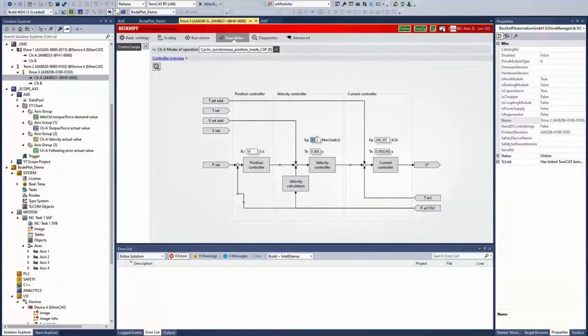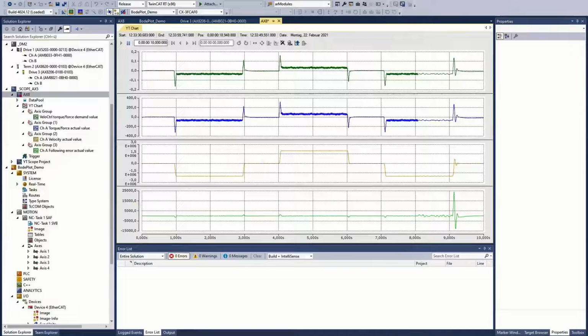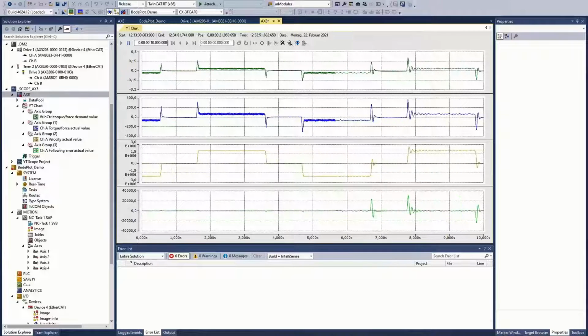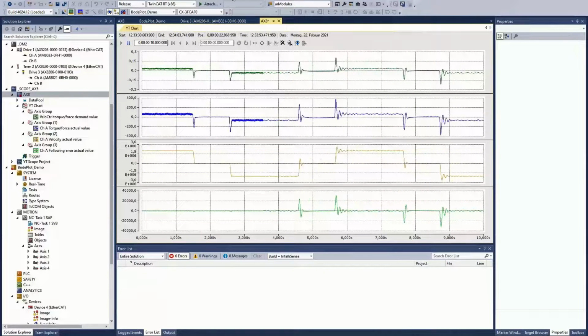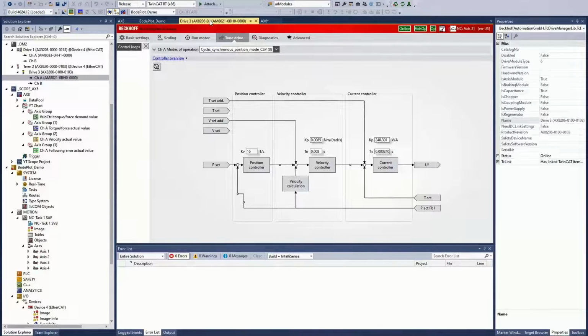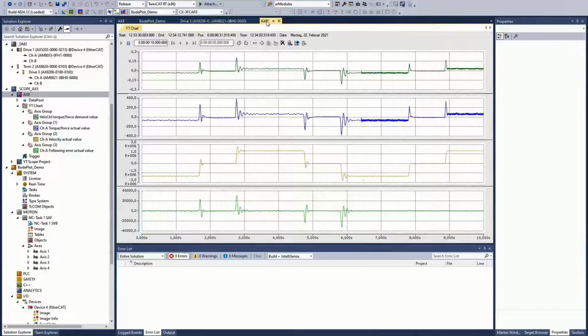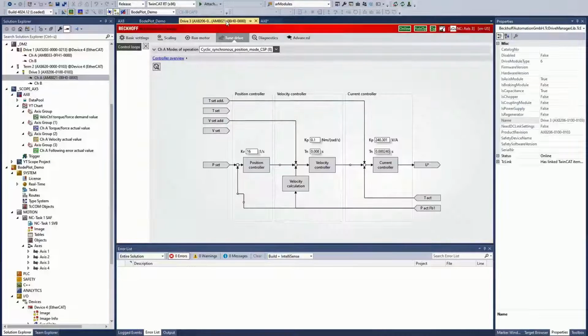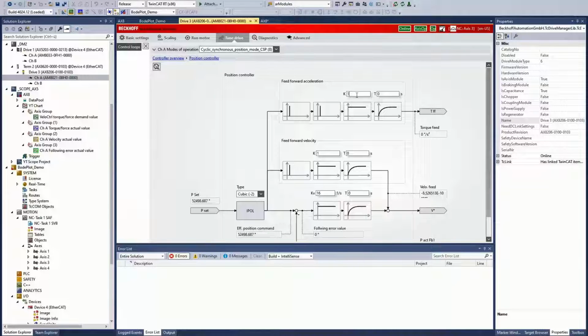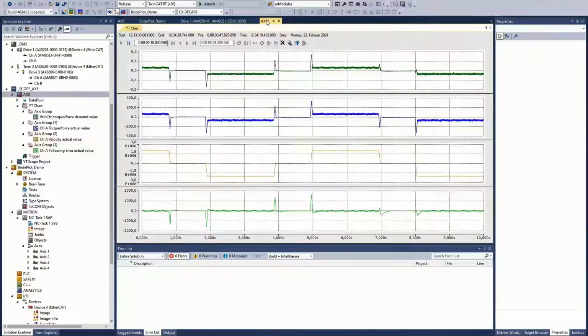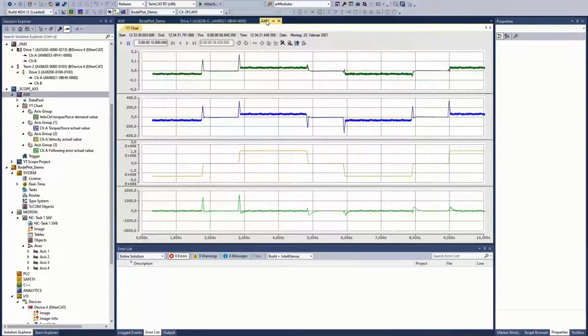And we go back here to the default gain, then we can compare it easily. You can see there is no vibration or oscillation in all curves. So it was really helpful to tune this axis, going back to our improved figure. And then the last step is the acceleration feed forward, maybe 100%. This is then minimizing the position error again.